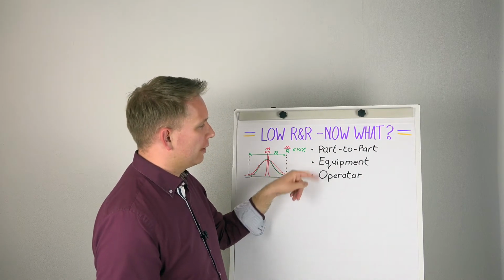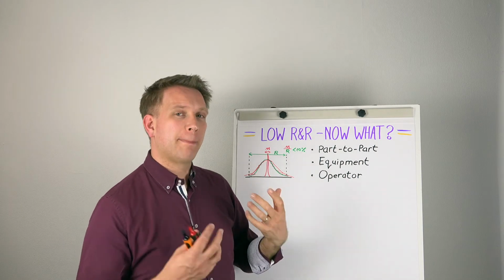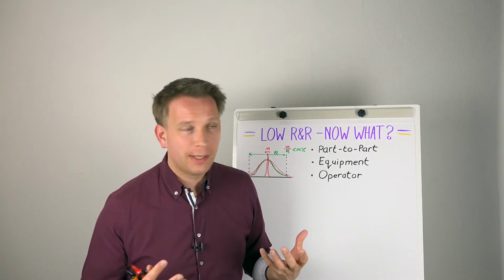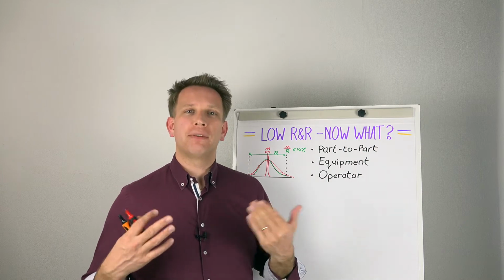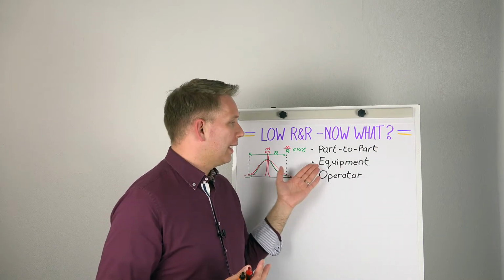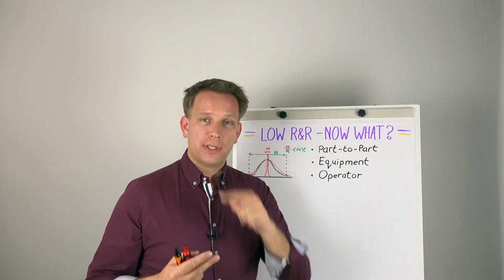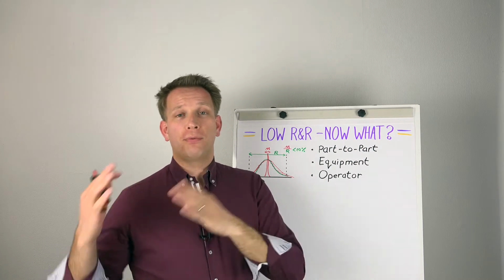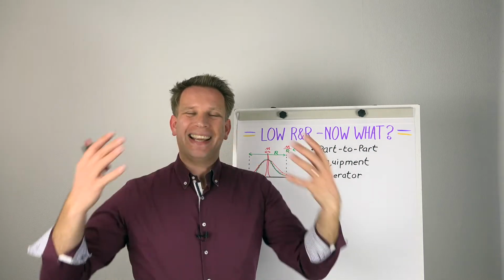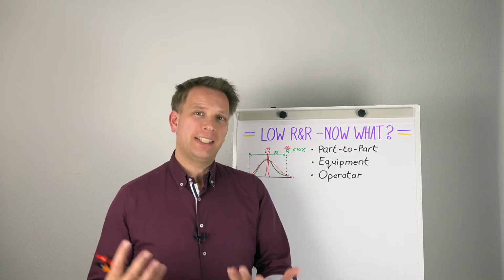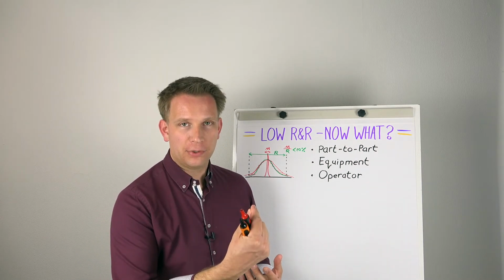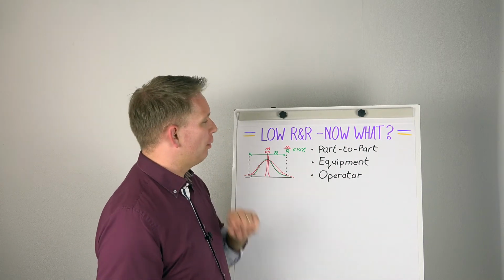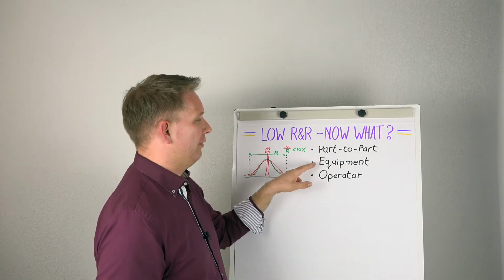And this one, I mean, 3 measurements might sound like not so many, but actually we're doing that 30 times, because each operator has 10 times that you do these 3, but also we have 3 operators, so we're checking that whole bunch of 30 times a comparison of 3 values that measure the same thing, and we all put it into the equipment variation.